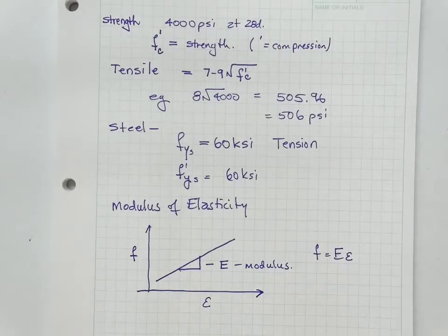We can talk about them interchangeably because they're the same thing. I can stress a structure or I can strain it. If I strain it, I induce a stress. If I stress it, I induce a strain. But it's kind of hard to tell the difference, right? Because I'm going to do the same thing. If I pull on it with a force, it'll stretch it a certain amount. The elastic modulus, Young's modulus, is fairly old, in the 1760s, I think, if I remember correctly, looking at the properties of wires and various other things. And so the elastic modulus is important because it tells us how much things are going to deform.